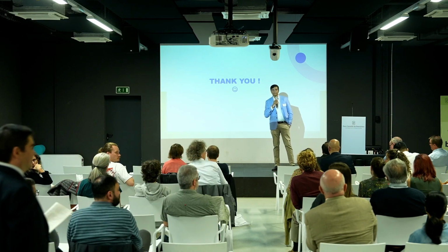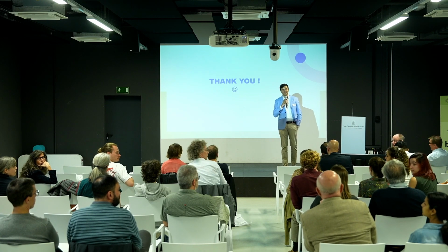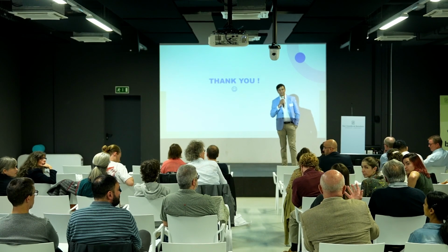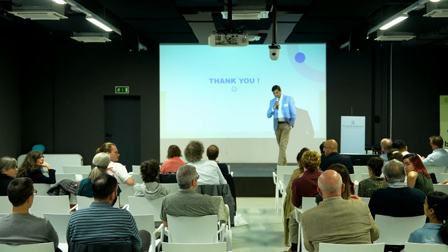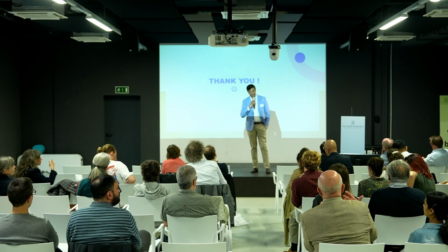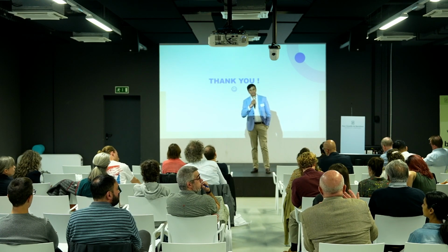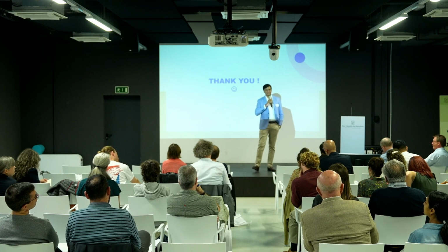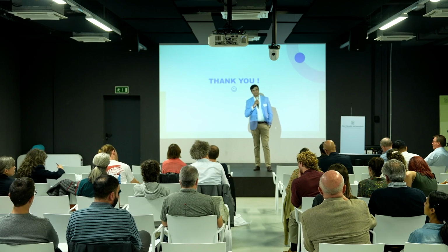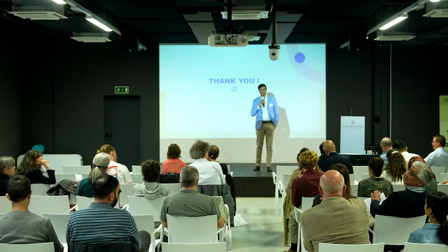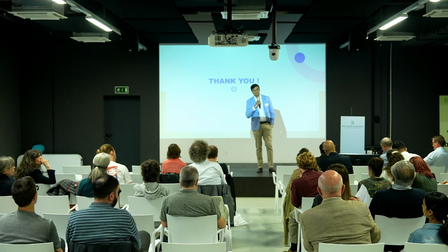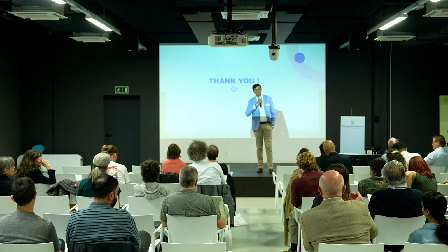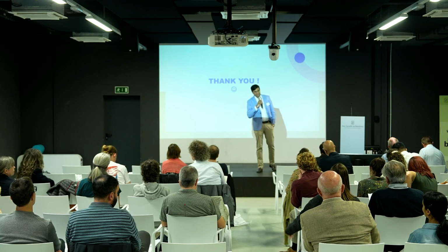Hi, very good presentation. I actually have 2 questions. One is related to your experience on HME right now: what is the lowest temperature at which you can effectively process and generate a formulation by HME? As you know, the main issue is thermal; it is very difficult to handle thermally unstable drugs. And of course, it's always a matter of temperature versus time of processing. So what is your experience in that? Do you have a sort of criteria to determine the lowest limit at which you can safely handle a molecule?